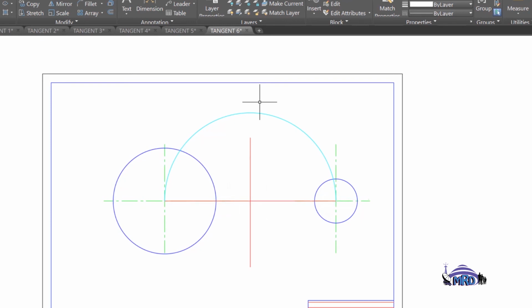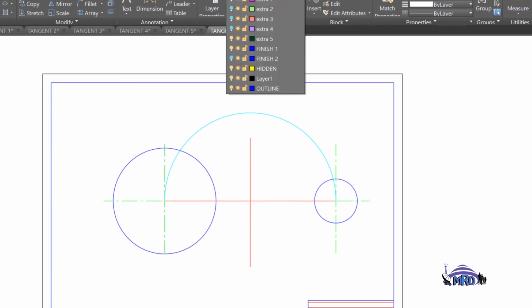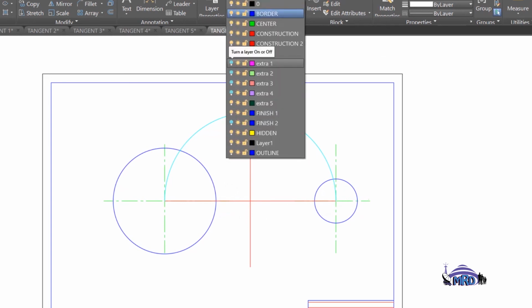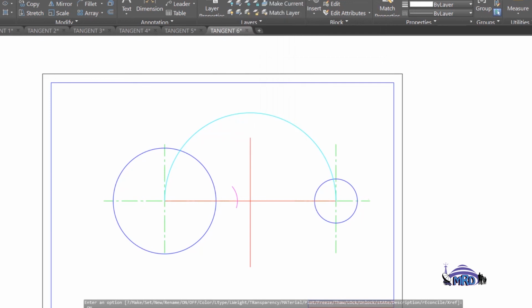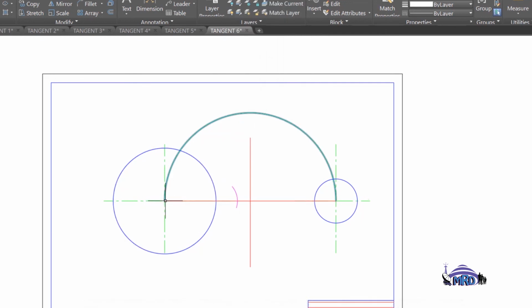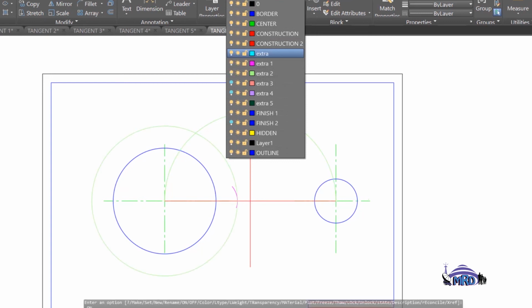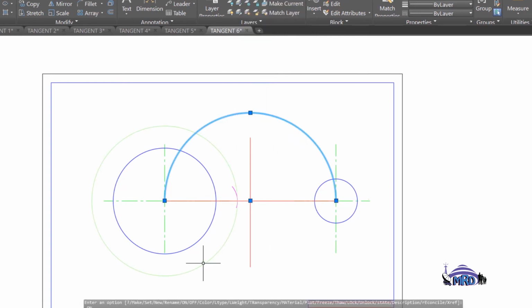So we'll end up producing a bigger circle on this construction. So let's just show what we would have done. We would have marked off that 25 radius. So now we can open our compass from the center. If we were doing a manual drawing in CAD, you would now drop in a new circle equal to this distance, which should be 25 plus 60. So that would be 85 for that distance. So that is the radius of the big circle that you're going to produce. And you will drop in now that new circle. So that circle is there now showing on the outside.